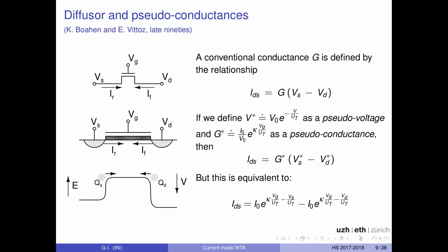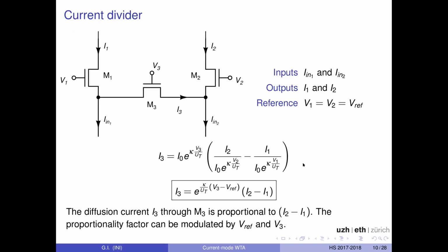So in these two parts of the world, independently, in one case pushed from industry, in the other case pushed from academia, basic research, they came to realize that you could use transistors in the subthreshold domain to do computation. And both Eric Vittoz in Switzerland and Kwabena Boahen in Carver Mead's group at Caltech proposed such a circuit, which is called the current divider, to implement resistive networks.